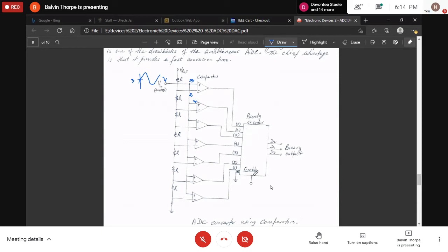So what happens is that when it's that signal for the voltage of 3 based on the comparison, a binary representation for this value at the input of the encoder is going to be outputted here on D0, D1, D2. And if it was 3, then this would have been a 1, this would have been a 1, and this would have been a 0.